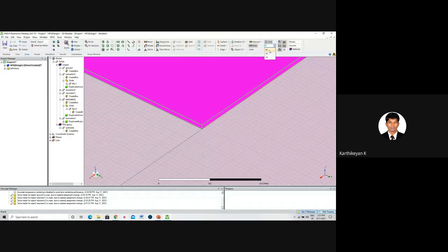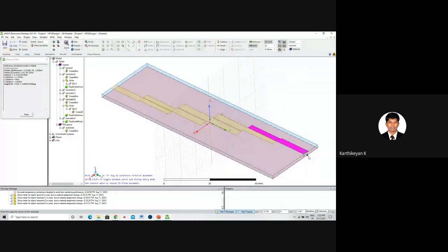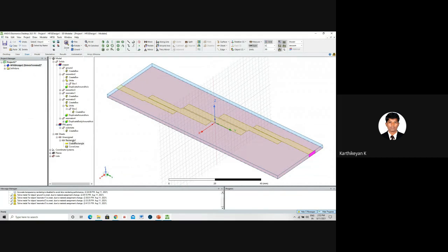Okay. So here you can see in the top right, the plane is there. So we are actually in XY plane. So the perpendicular plane is actually the XZ, which you can see in the bottom right. So XZ is this perpendicular plane. So go to draw a rectangle and draw a rectangle at this end, this side, and then go towards the bottom. So the rectangle is created.